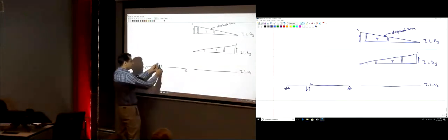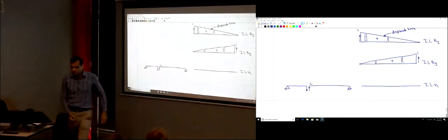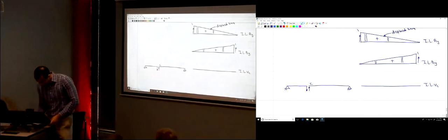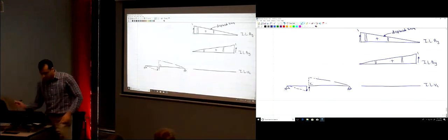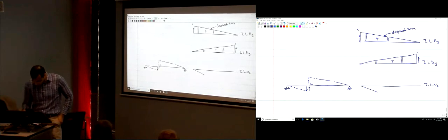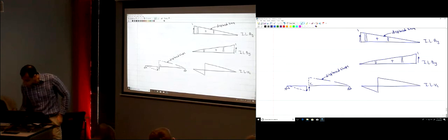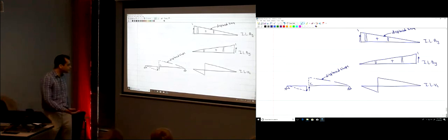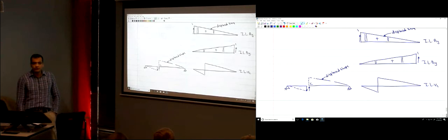Then I'm going to move the unit displacement like this. I'm just going to move this down and this up. And this is the displaced shape. So the displaced shape looks exactly like the influence line. This is how the shape of the influence line of that function looks.